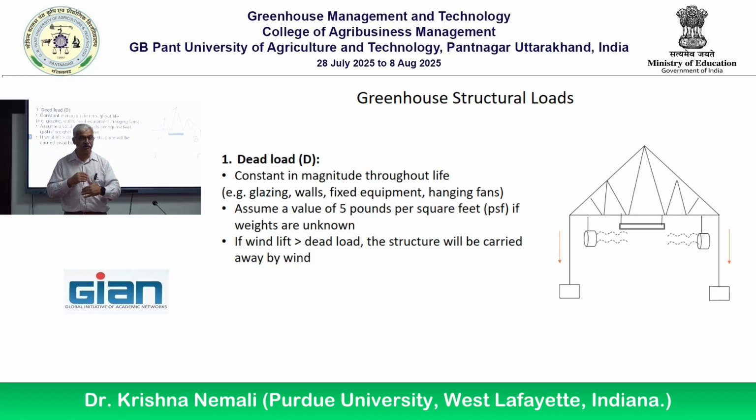Higher the pitch, more transmission, because angle of incidence is less. Those kind of technical things are very, very important in decision making. They will have a permanent effect on your greenhouse. If you already put your money onto it and made mistakes, you can't change it. You have to reinvest and change the roof. It can cost a lot. So before you invest on anything, knowing this is important. That is the only purpose of this lecture.